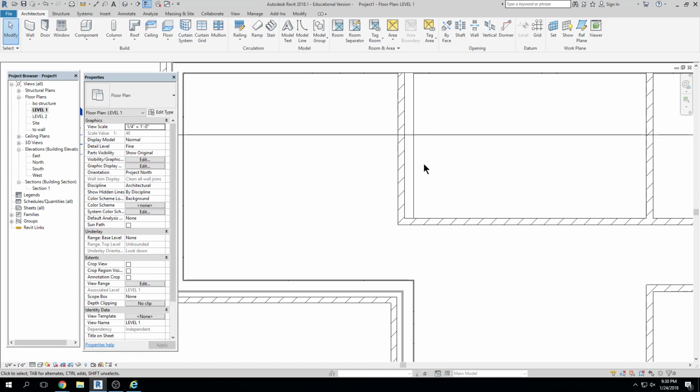The system works, right? And you're going to do this with everything in Revit. So walls, doors, windows, storefront, families, other components. Instead of creating a brand new one, you're going to grab the thing closest to whatever you want. You're going to copy it, rename it, redefine it, and then use it in your project, essentially. Once you do this 4 or 5 times, it will get very easy.